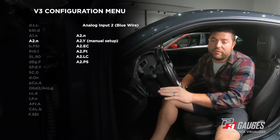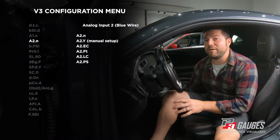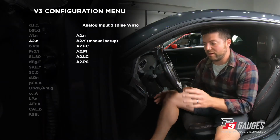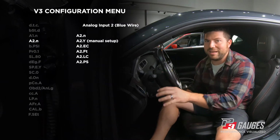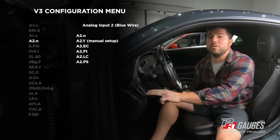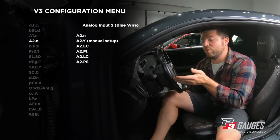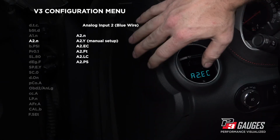So these pre-configured configurations are just so that you don't have to manually put those low and high values in. It's going to be already populated based on the sensor that's connected to it. And this is going to be, again, for the blue wire on your harness. Analog input 1 is brown, analog input 2 is blue. So now we can go to our next setting.